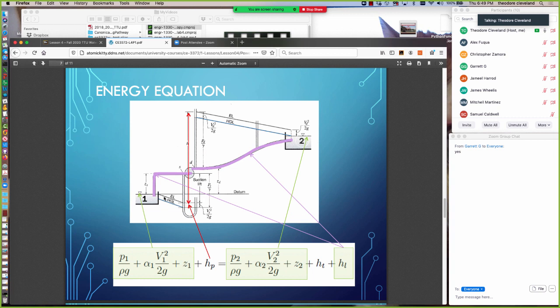And then the energy, or the head, when it gets to the pump, is down here. So this energy line, it has slope because there's energy loss along the way. So the total head starts at the pool elevation of the reservoir and declines as it makes its way to the pump. Then when it gets to the pump, a certain amount of head is added, which is depicted by this red line segment here. And now the energy line is up here, and then it declines as it makes its merry path to the outlet.